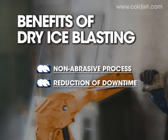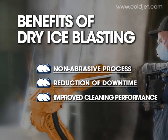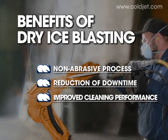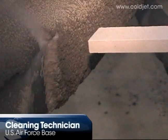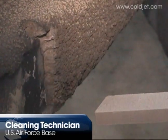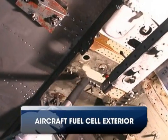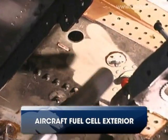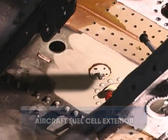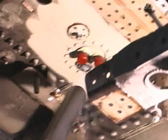A third benefit offered by dry ice blasting is improved cleaning performance. In effect, a cleaner clean. We found it to be outstanding at cleaning parts of aircraft that were normally very difficult to clean. All of the structures are bonded together with sealer, and the ability for the sealer to have good adhesion to the airframe components is completely dependent upon how well the structure has been cleaned.